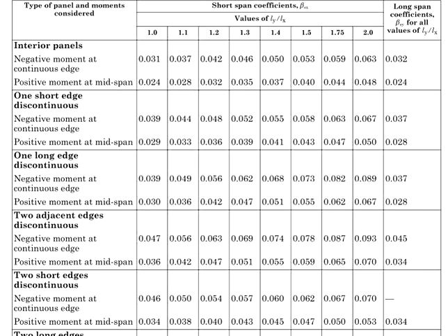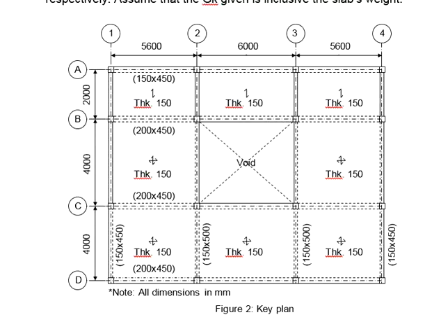There are several ways to do it. You can choose to design every single moment, provide the reinforcement accordingly, depending on the magnitude of the moment, so that the slab can pass. However, in practice, normally we design for the largest moment and apply to all. Why is it so? First, you know a typical slab is a large panel, probably the largest structural element in a skeleton frame system of an RC structure. In terms of the amount of concrete relative to the load, it is more than enough. In other words, you have plenty of material for the slab to carry a little amount of load.